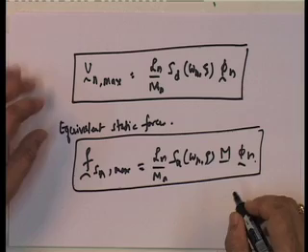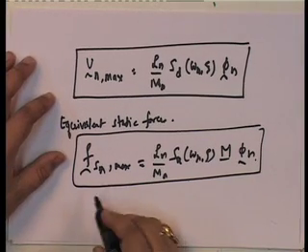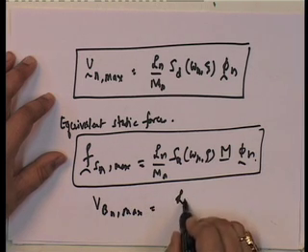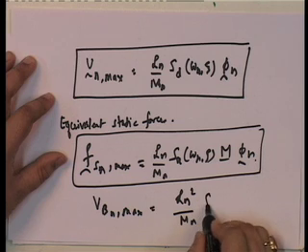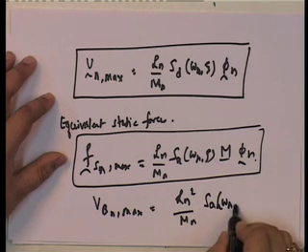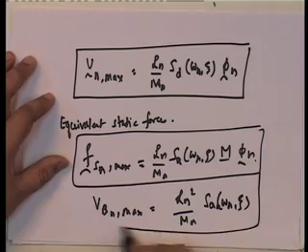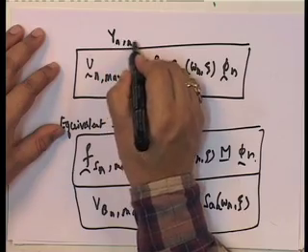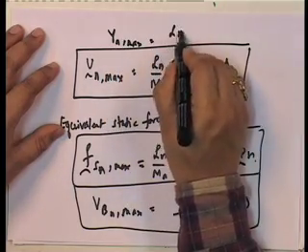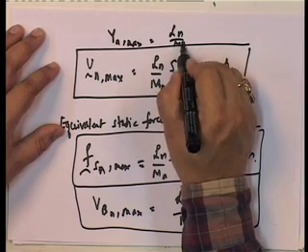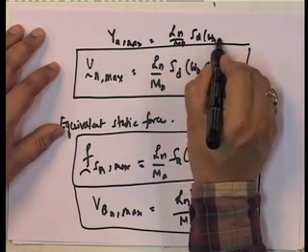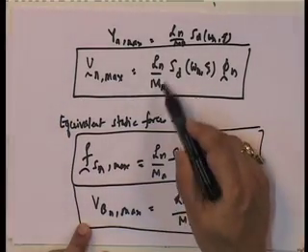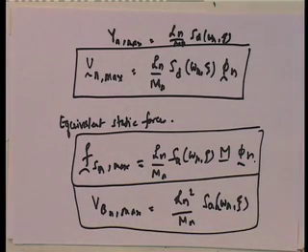So this is a specific thing, and then finally, Vb, the base shear in the nth mode, is given by Ln squared upon Mn into Sa of omega n, xi. And I will write down on top, yn max is equal to Ln upon Mn into Sd of omega n, xi. Of course, every term will be different for different modes.